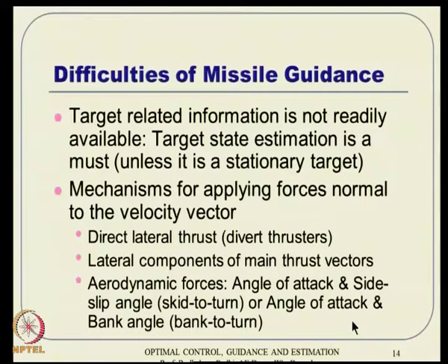So, that means you can consider the side slip angle as something like angle of attack, and both angle of attack and side slip angle can be generated utilizing the control surface deflections, and that concept is called skid to turn. And suppose that mechanism is not there, the vehicle has only 2 big wings and all that, that is also possible, and especially for long duration practical things, typically people do that to minimize the drag actually.